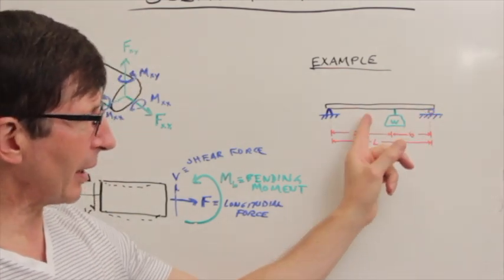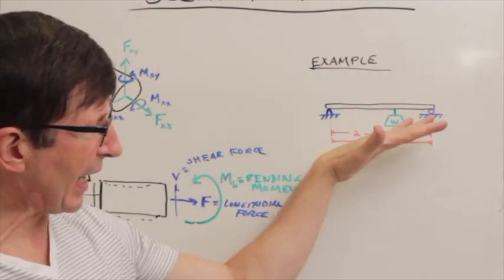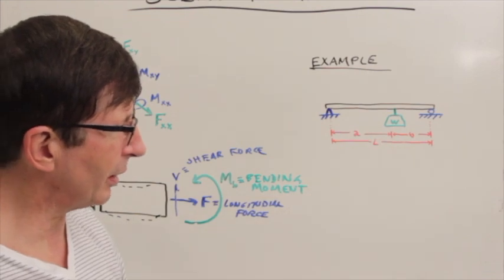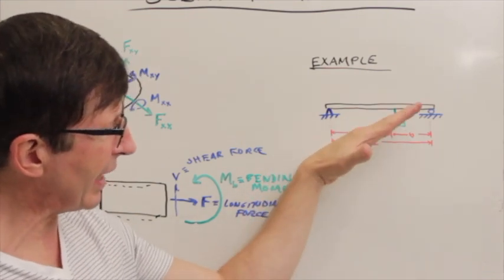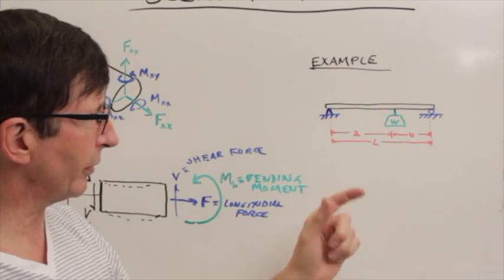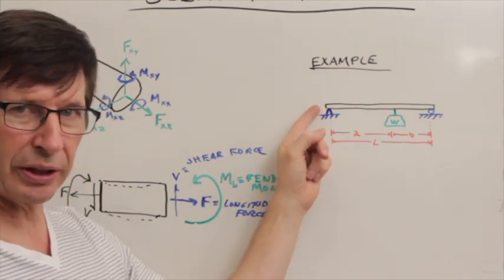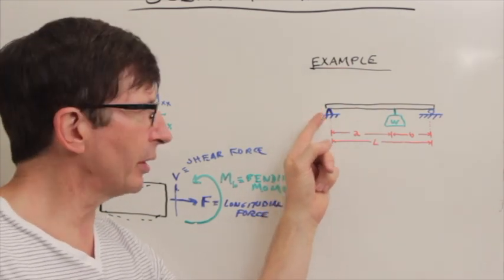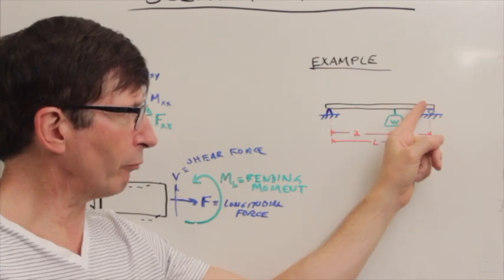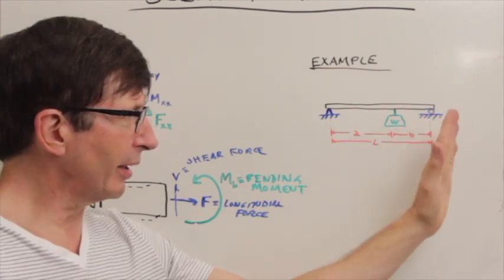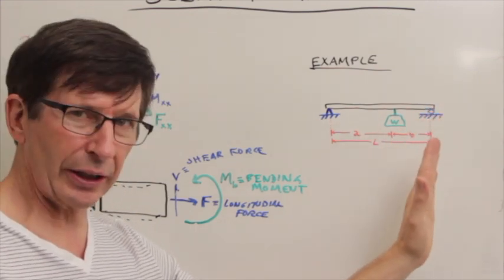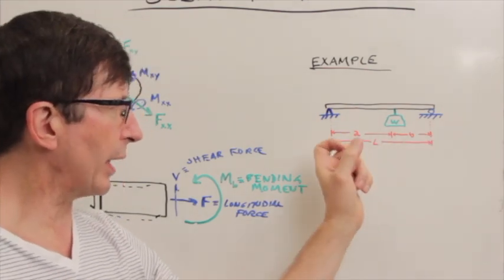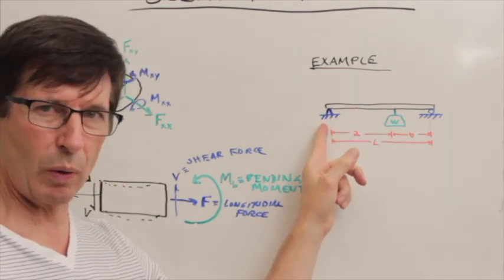And because, like a pin, there's nothing preventing an angle from happening there at the end, it allows rotation. So here, rotation is the only thing allowed, and here we permit rotation and a translation in the x direction, fixed in y, fixed in xy.